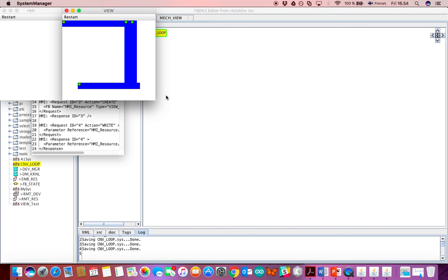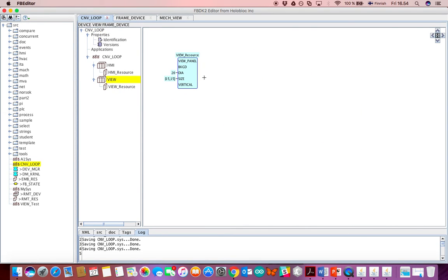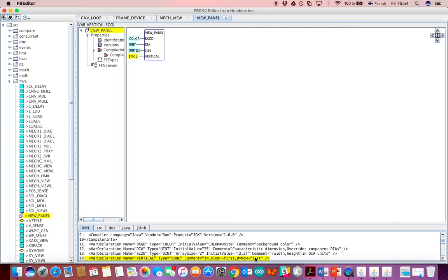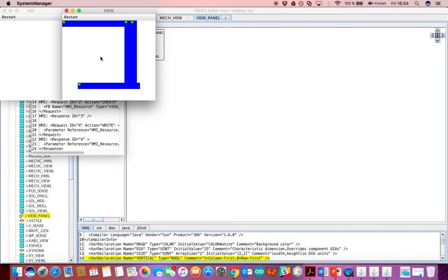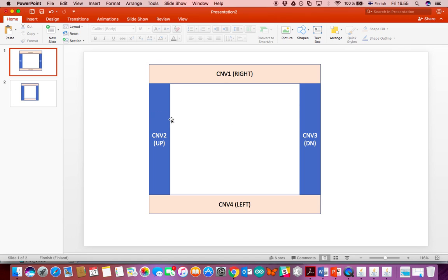As we look at this interface and remember the resource, we have a vertical input here. It means that by default it fills row first. We place different components until we have space. We place first, we place second, we have a third one, and then we need to put the fourth one. But this space is already occupied, and therefore this segment goes here. In principle, it's possible to put column first, and then this conveyor segment starts to appear below. And this is the first place where you can start to control where and how you would like to arrange it.